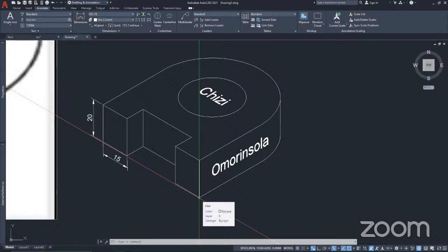For the obliquing also, you have to try what works. You want to oblique to a direction, and one of the directions needs to be 30, and the other one needs to be minus 30. So if you're obliquing to the right, you use 30 degrees. If you're obliquing to the left, you use minus 30 degrees. Do you understand this?